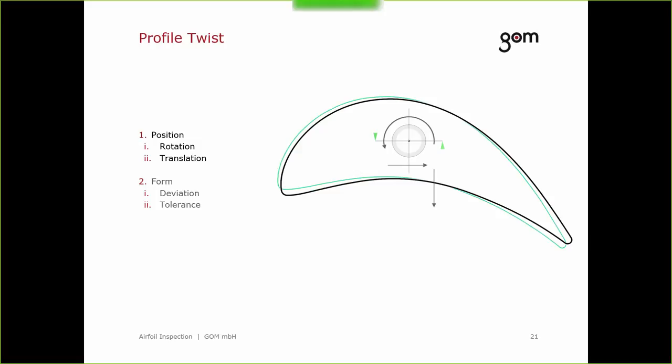During the alignment, all 3 degrees of freedom are calculated simultaneously. These are the rotation about the normal of the section plane and the true translation in the plane. To ensure this is clear, I will show the 3 components of the alignment separately. The origin of the reference coordinate system for the alignment is created at the intersection of the world z-axis and the plane of the section.